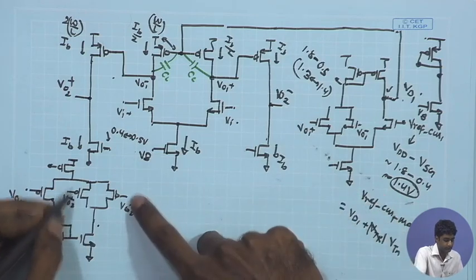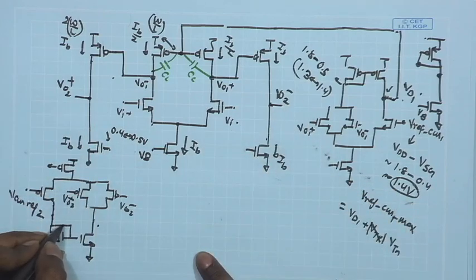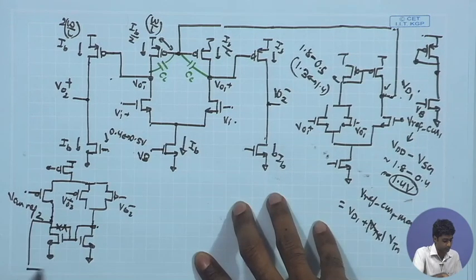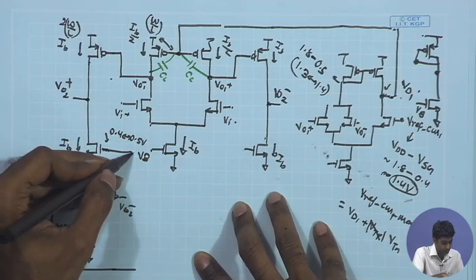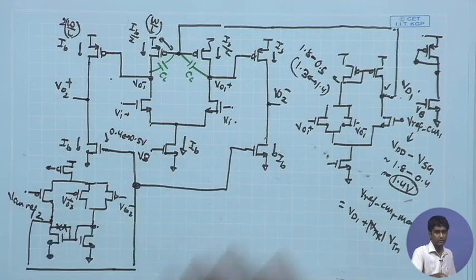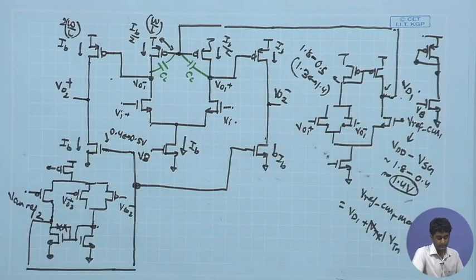So in order to do that, if this is going up, I need this particular output to control the gate voltages. The way I have drawn, I just need to flip this diode connection. I need to draw it this way. So this will be my output node, the high gain output node. The diode connection will be made on the other side, and then I can bring it over here and connect it with both the gates. So this is going to complete the common mode feedback for the second stage.